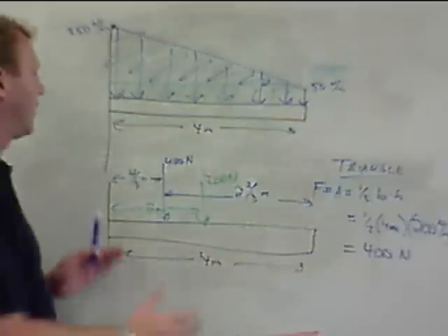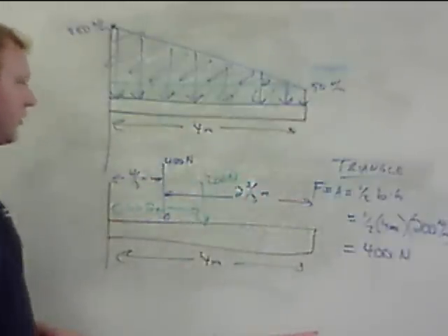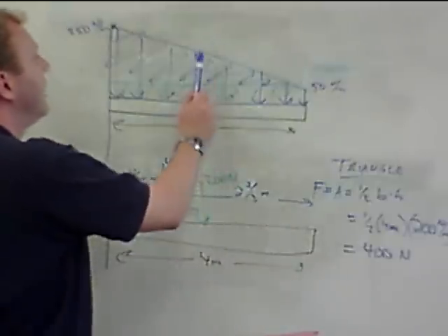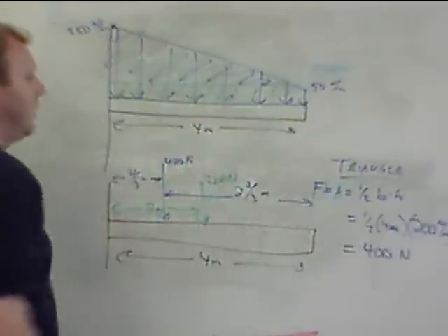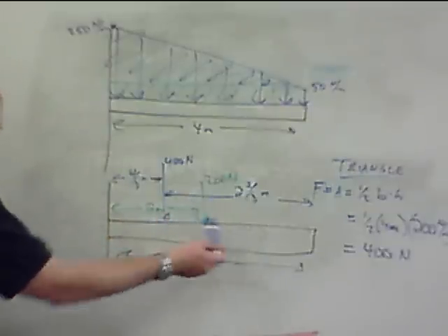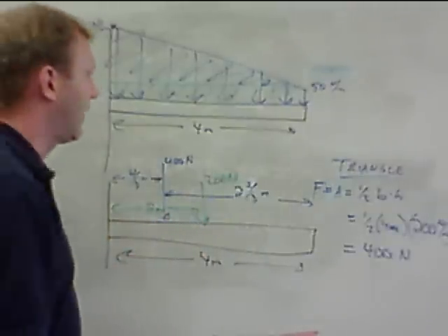So again, we end up with 1/3 of the distance here, 2/3 of the distance there, and we find that we have simplified this distributed load into 2 forces, and we can treat these 2 forces as point forces acting on our beam and find net force and moment.